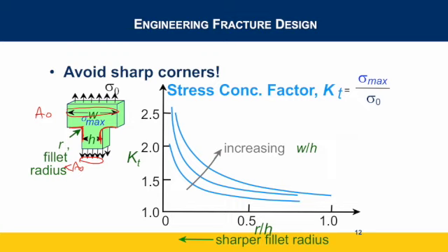So in this one, essentially this is a small rho sub t, whereas this one has a much larger rho sub t. And then I have a void defect length of A. This one has the same void defect length of A. So in this case, with a much smaller rho sub t, it would want to crack at this position, but if I blunt out the curve, I reduce the localized stress and I minimize the fracture of the material at that point. Okay. So again, this would be my rho sub t, and then my distance in would be my A.